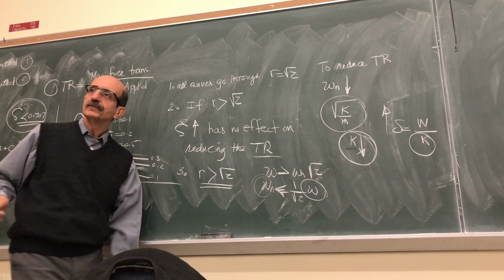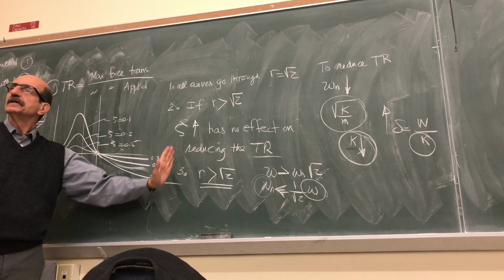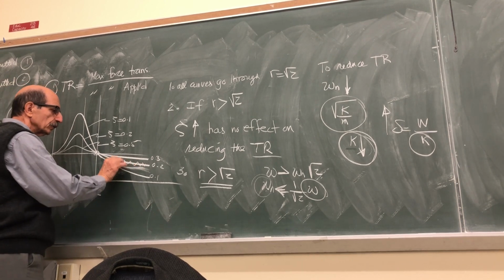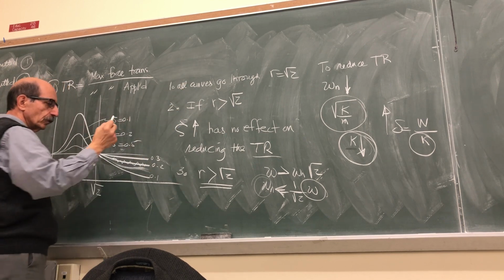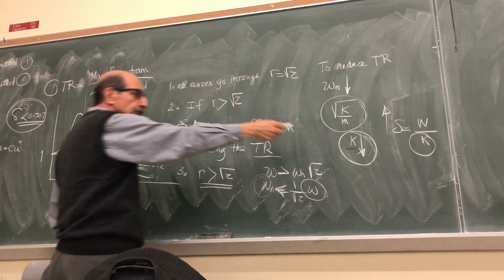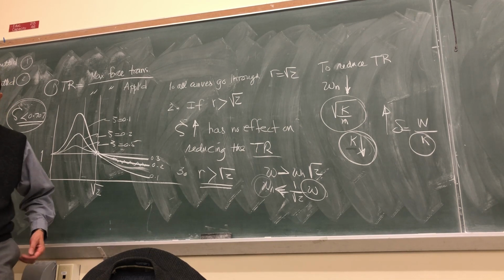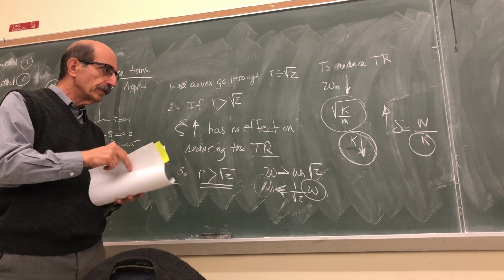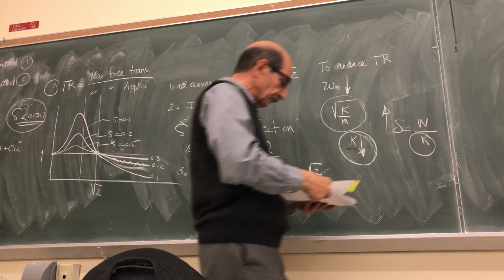With damping it is clear. Damping, you saw that. For vibration isolation, if you're beyond this, in fact, increasing the damping doesn't do you any good. So if you consider just a particular case, you want to reduce the transmissibility ratio, the way to do it is just going further and further here, which means reducing K. So, did we do an example problem on this or no? Let's do an example problem before I get to the second case, which is the displacement transmitted. So I'll do a simple problem.